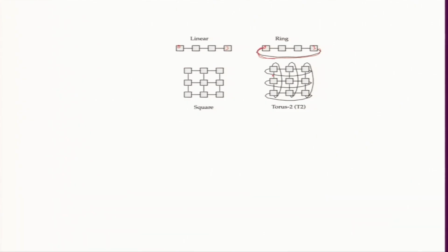So, what is the advantage of this wire? Right now it is all uniform. Of course, from 0 to 1 is 1 hop, 0 to 2 is 2 hops. Either you can take this side or that side, you can go this way, then that way. Okay. We added a wire, but this is more like a uniform structure, it is called a ring, and at least the maximum distance we have covered, we have made it half. So, ring is useful for simple one wire connection and it makes the maximum distance half, right. Is it not n by 2 now?